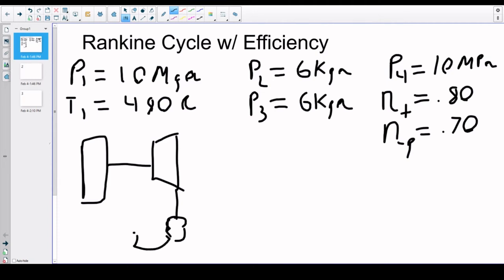And that completes the cycle. And these are just the state points, so you know what each one refers to. And then I think I draw the work out of the cycle and the condenser heat leaving and the work of the pump that has to go in.